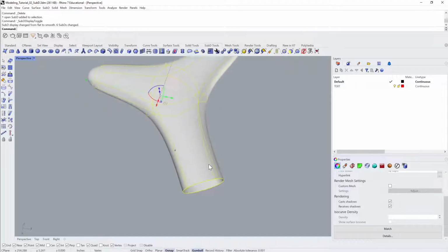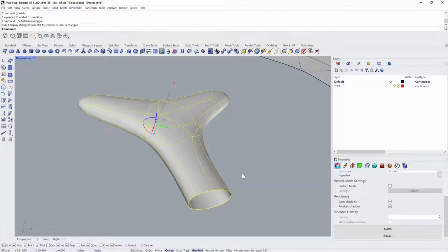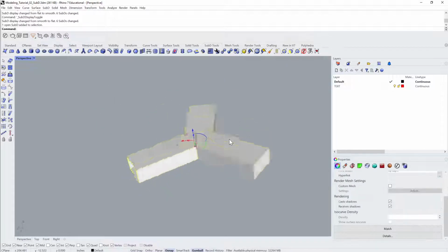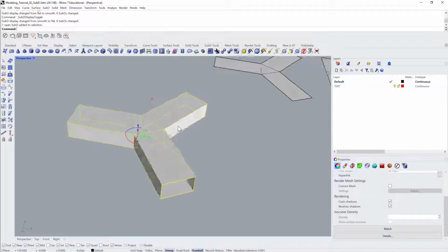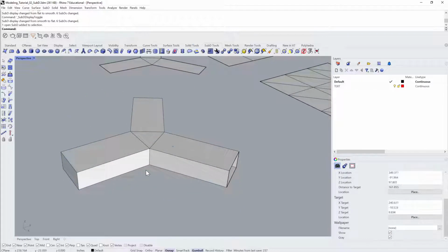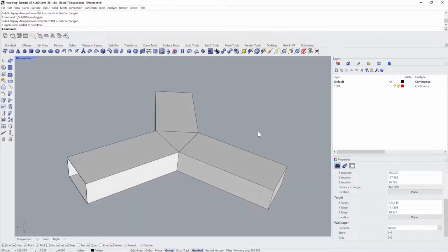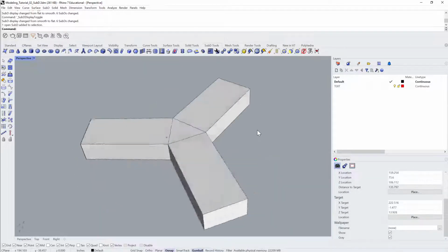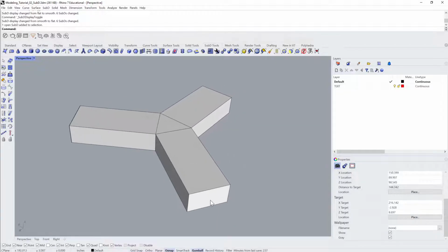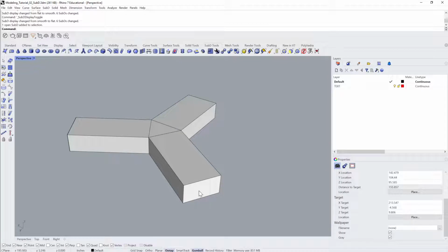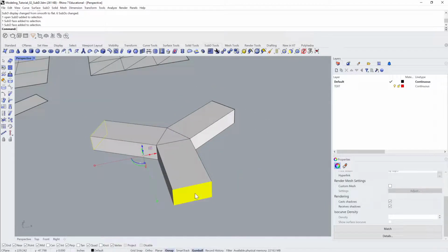You can see here that this is giving us a much sharper edge around the end of this tube versus the other ends, which are capped. So having open geometry, an open edge, will tend to introduce a crease to geometry. Understanding how to insert surfaces, extra edges, to control the way that geometry smooths is the key to subdivision surface modeling in Rhino or other programs. So what do I mean by that?